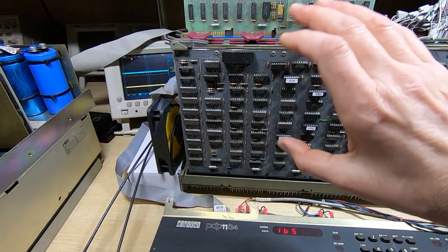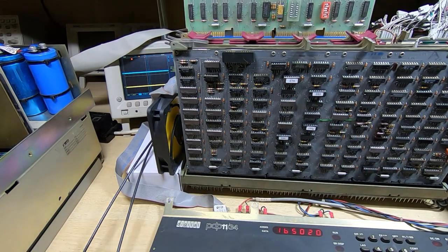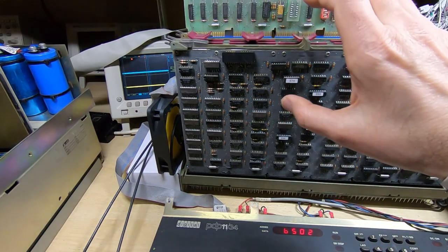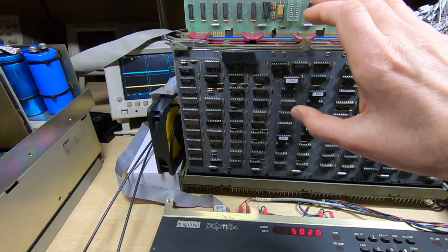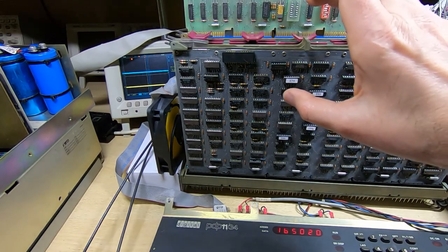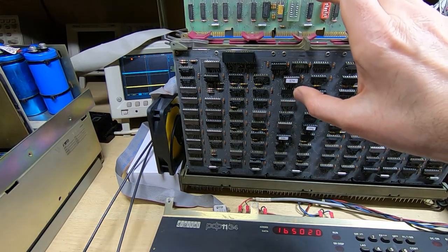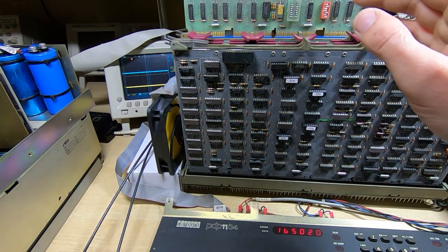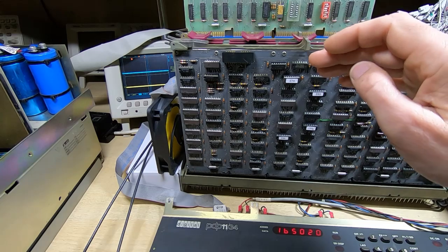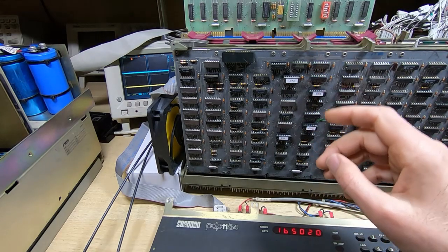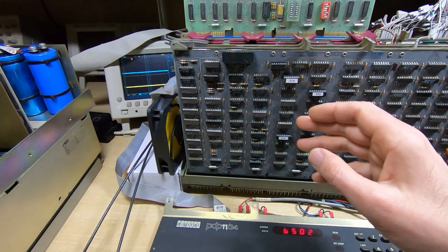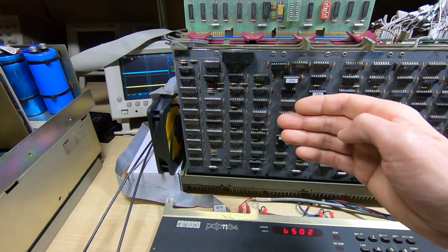Now it says it's a control and status register, but they're not really registers. They're a collection of circuits that are accessed through that address. Which particular circuits you access at any one time depend on the current state of the state machine. The second of the two addresses is the data transfer port, and again it will vary in its function depending on the current state of the state machine.